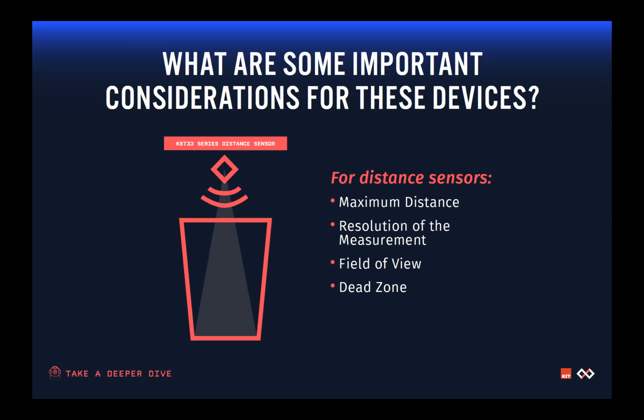The only encouragement I give you about maximum distance is to be sure to optimize that and measure the object that you're trying to measure in order to apply the data. In other words, if you don't need to see the full 30-meter length of an entire grain silo, maybe you don't want to put in a 30-meter type of distance sensor. So think really carefully about that maximum distance. You also want to be able to see the bottom of a trash bin, for instance, as depicted in this picture.